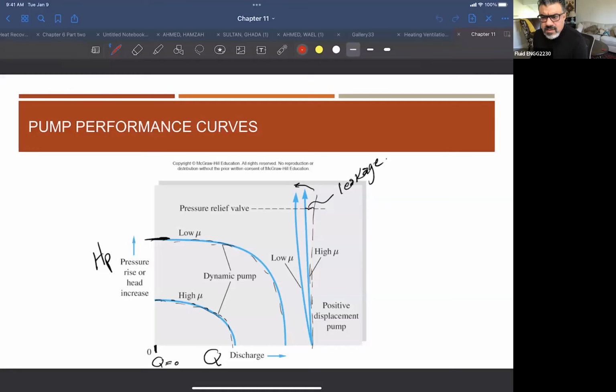So if this pump is connected to a long line which has many resistances, the pump will be able to overcome these total losses by increasing the pressure at the outside port of the pump. We call it the delivery side. If you disconnect the pipe and measure the pressure at the exit of the pump, you will not see the same value of the pressure.